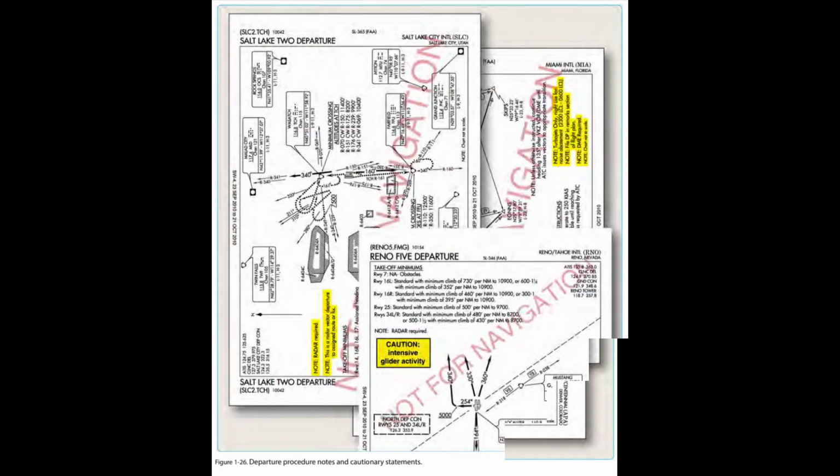SID flight planning considerations. Take into consideration the departure paths included in the SIDs and determine if you can use a standardized departure procedure. You have the opportunity to choose the SID that best suits your flight plan. During the flight planning phase, you can investigate each departure and determine which procedure allows you to depart the airport in the direction of your intended flight. Also consider how a climb gradient to a specific altitude affects the climb time and fuel burn portions of the flight plan. Notes giving procedural requirements are listed on the graphic portion of a departure procedure, and they are mandatory in nature.